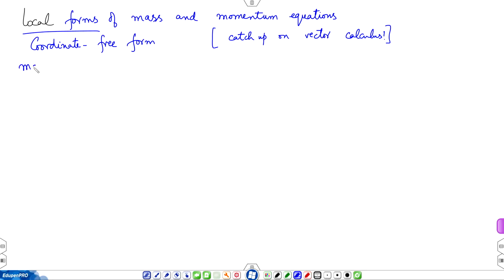the mass balance equation. This is the incompressible form of mass balance equation. What is the momentum equation? It is just mass times acceleration is equal to sum of all external forces. External forces are body forces and surface forces. Now, we dropped the control volume. We said let control volume shrink to a continuum point. This is equivalent to saying we are doing calculations on a unit volume basis. So, it is mass times acceleration on unit volume basis, which is density times acceleration.